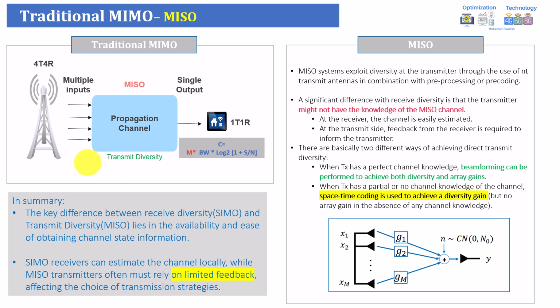Now, assuming that the UE doesn't have any knowledge, or has only very partial knowledge, about the channel, it doesn't know what is happening in the channel, so it cannot make this kind of beamforming, or in other words, the array gain directed towards the user in a static beam or whatever. It cannot do that if it doesn't have the feedback. So in this case, what will happen? It will use another technique, which is called space-time coding.